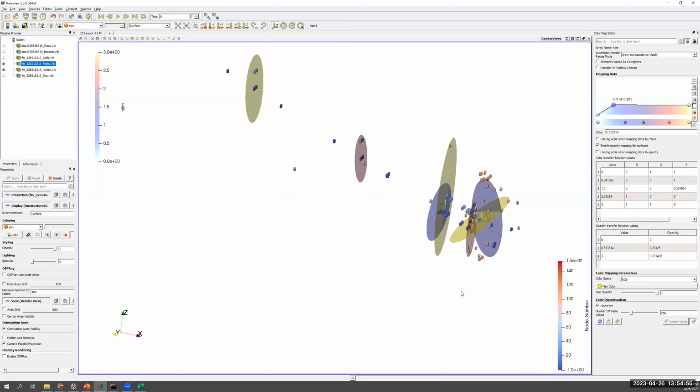And then as you increase the flow rate even further, you'll end up at a point of diminishing return where the flow that's coming out is now too cold to use for electrical power production. So you're no longer getting any benefit from flowing so hard. On top of that, you're going to have higher pumping losses, also hurting you. So there's definitely an optimization on the flow rate that will be best suited for power production. And that optimum flow rate depends very heavily on a lot of things. And that's exactly what GeoDT is meant to be looking at, to help out with that type of question, is figuring out the best flow rate to use.